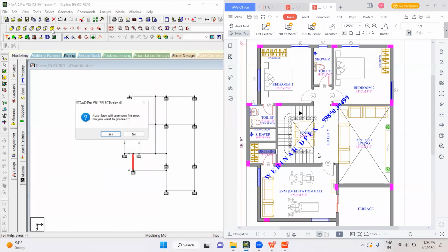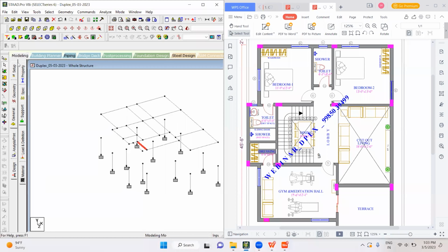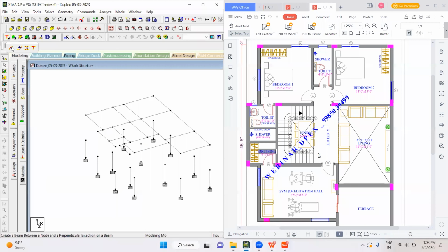In isometric view, now I'll select this first option, select this, and then add a beam like this using the beam cursor. This beam is not required, delete this. I'll go to plan view and select this, and then geometry, merge this member, say merge, okay. Right? This is now absolutely done.